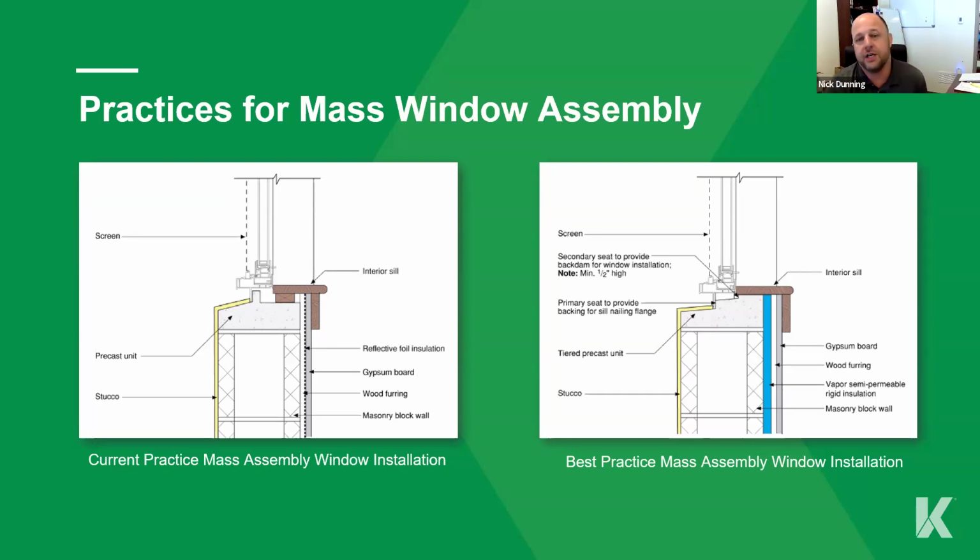You also have to understand it is not a bathtub. Urethane, when it sits in ponding water for longer periods of time, is going to break down. So we want to make sure we're sloping properly, getting the water off. As David Karins always reminds us, use gravity, it's our friend. So let's make sure we direct the water away. But you really should plan on about 5 to 10 year cycles.